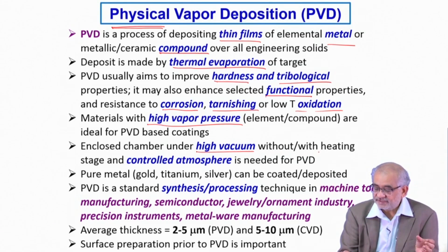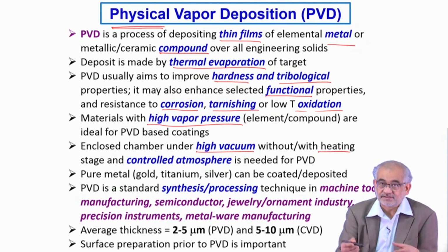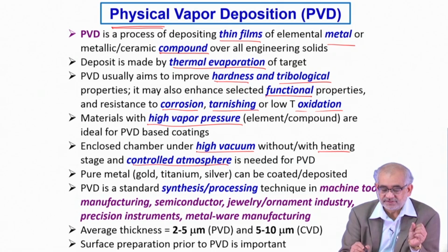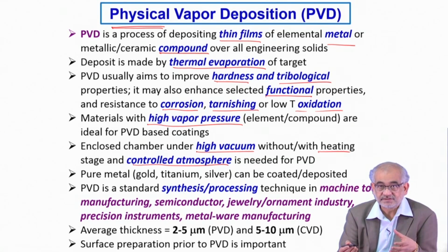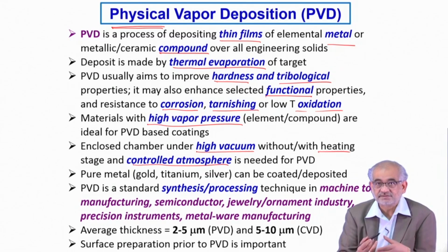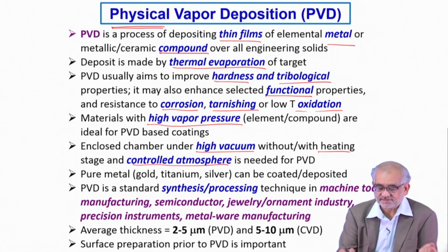We may have arrangements for heating, may not have arrangements for heating, I mean ancillary heating processes for the substrate. We should also have a controlled atmosphere, which could be simply rarefied chamber, high vacuum, or inert gas like argon, or we can even have a reactive gas in some very special cases.